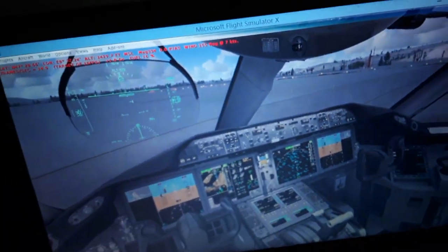So we have runway 14 at Zurich International Airport, LSZH. Over here you can see this runway for takeoff and for landing. So we have the ILS localizer tuned with this radio frequency. We're also going to tune the magnetic heading of the autopilot director system panel, so we're aligned with the runway heading like this for landing and for takeoff. And we have also the ILS localizer.